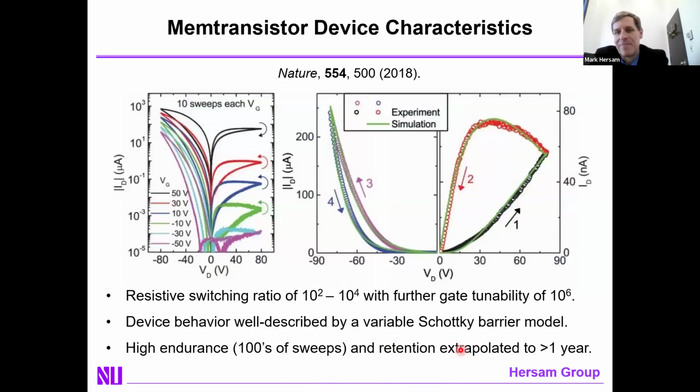These were some of the first memtransistor devices we produced. They show the qualitative features of the device. And in particular, in the 2-terminal current-voltage response, you see a large memristive hysteretic loop. You will note that when you go to negative bias, the hysteretic loop is attenuated, and that asymmetry can be traced back to the fact that this is a device where all the action is happening at the Schottky contact, which will typically have some rectification character to it.